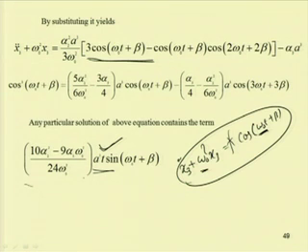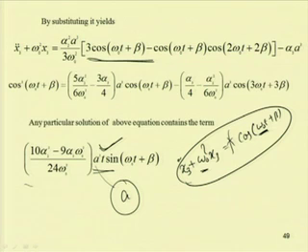This is due to the fact that the constant or amplitude response we have considered, that is A, we have not considered to be a function of the frequency. A is not varying with frequency, so the expansion method we did is not correct. So, Lindstedt modified this method by taking a frequency dependent amplitude term, and next class we will study that method, the Lindstedt-Poincare method, for finding the response of the nonlinear equation.